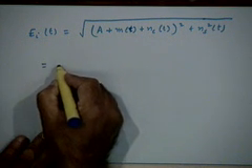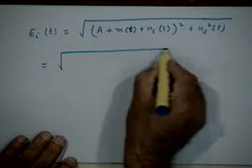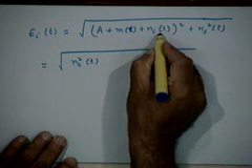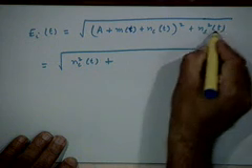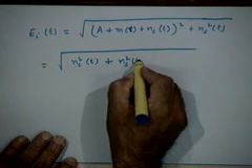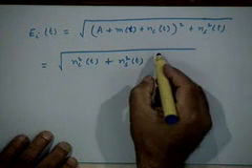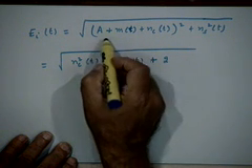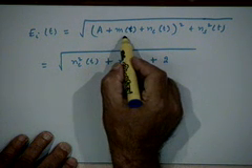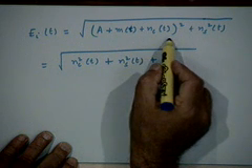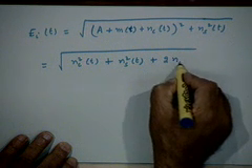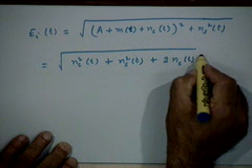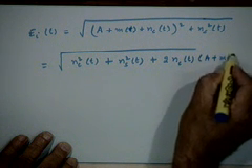So, if I ignore those square terms, this will be n_c square t, that is the term coming from here, plus n_s square t, that is a term coming from here, and then we also have a cross product term, right. I have only ignored the term (A plus m(t)) whole square, because that we are assuming is much smaller than n_c(t). So, the cross term will be 2 n_c(t) into A plus m(t), correct.